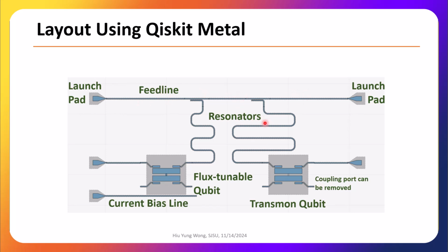So very often we share 2 qubits or even more qubits on the same line to save space. But we need to make them have different frequencies. So this is like frequency multiplexing. You can think of it this way. Some qubits, we make flux tunable, so we can change the frequency, right? Here, this qubit, we did not.